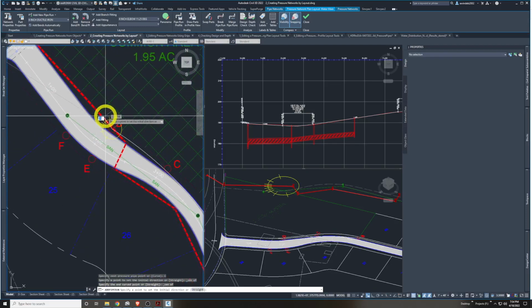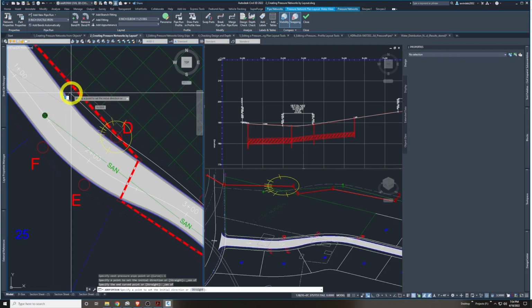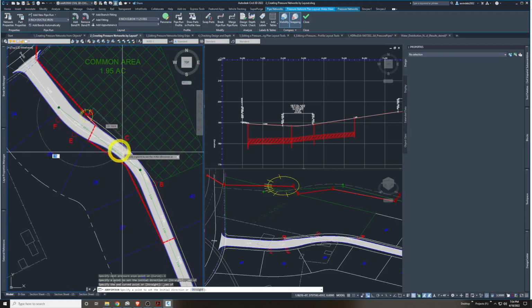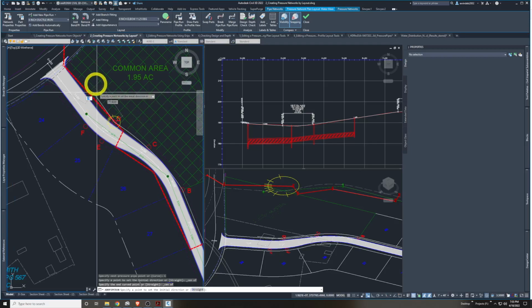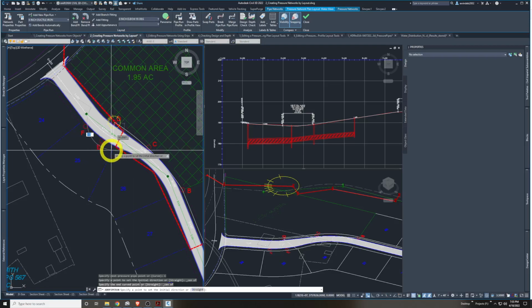We're back to the compass to say which deflection we can have here for a pressure pipe network. We didn't do it exactly like the book, but we generally curved it and are snapping to the right things. We're going to try to add a fitting now, okay? And we have our fittings here and here. Let's see what we got in here. We're looking for 6-inch elbow 90 degrees. There it is.